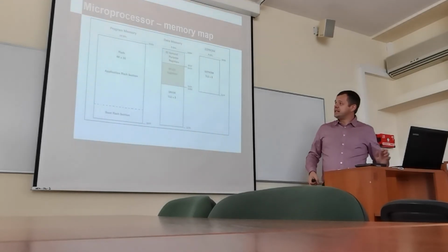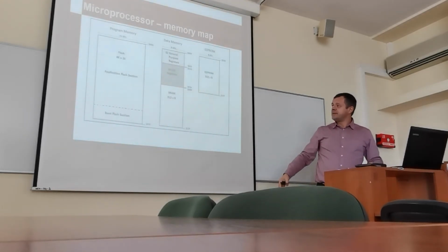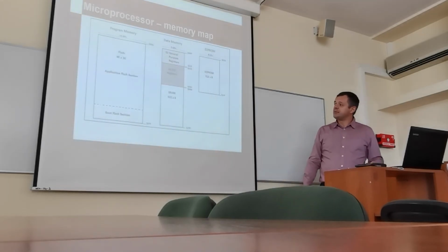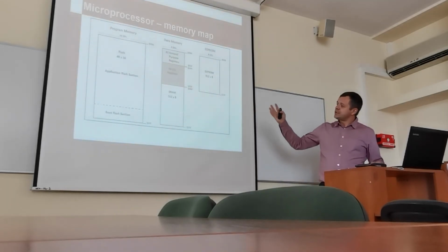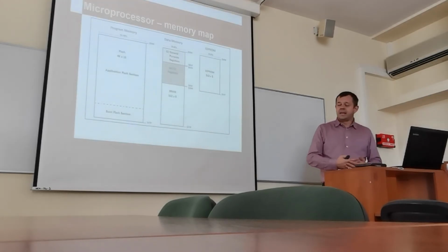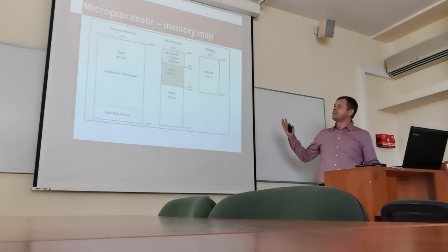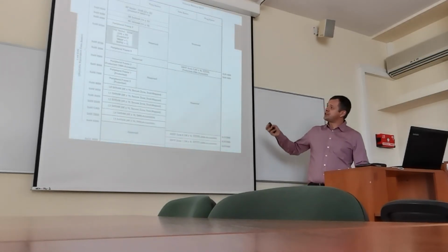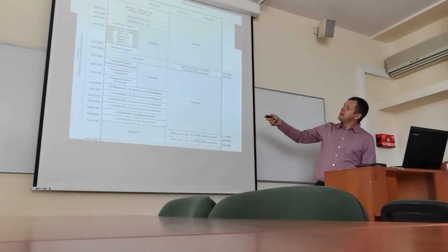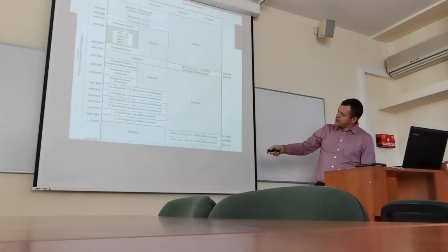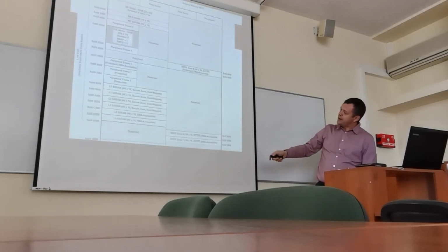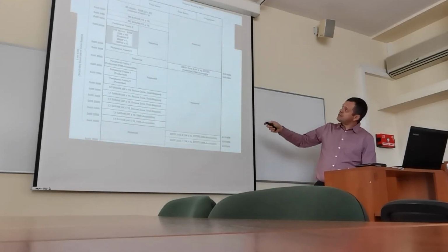The memory map is showing us what kind of memory is addressable under which addresses, and how to get to certain parts of memory. Because sometimes we've got a situation like in this memory map where everything is accessible just under different addresses. We've got different addresses, and then under this address is data.